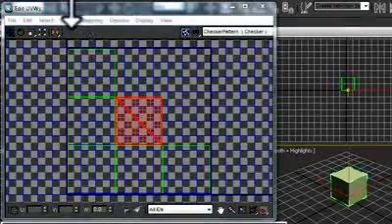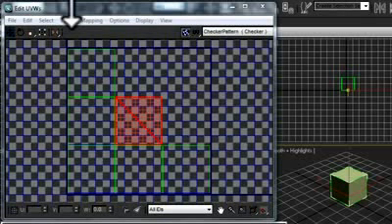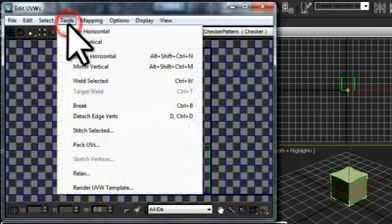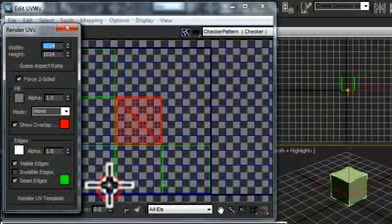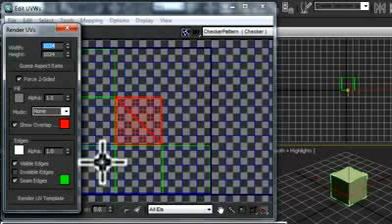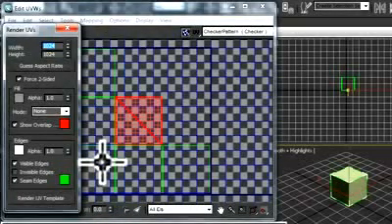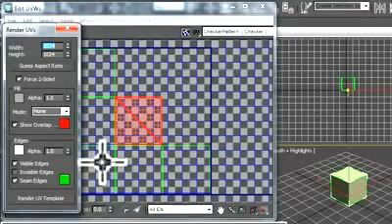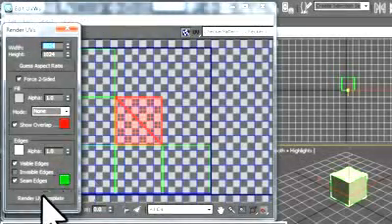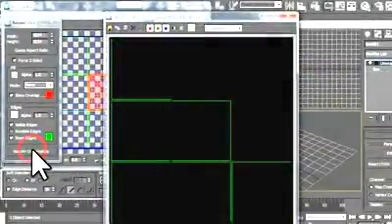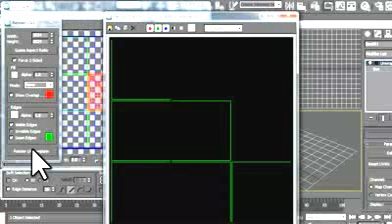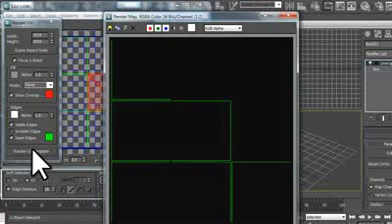Click on the Tools menu and select the Render UVW Template option. On the Render UVs window that opens, leave the settings as default and click the Render UV Template button. A render map will open showing the UVW map. It's very hard to see the green matte lines on this window. Let's save this UVW map to an image file. Click the Save Image button.